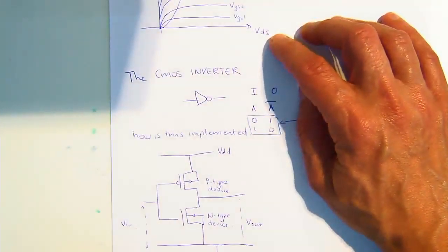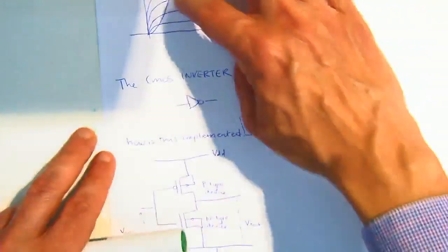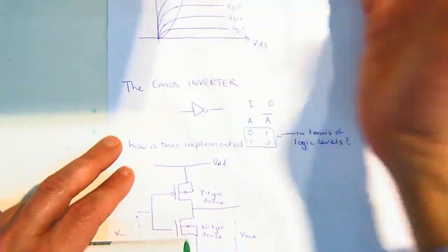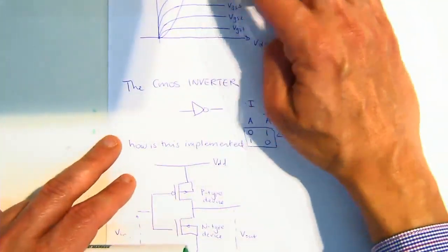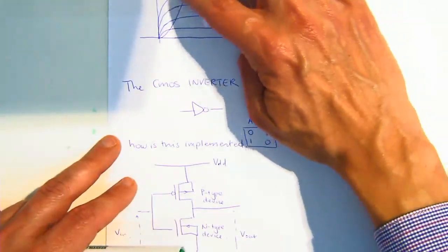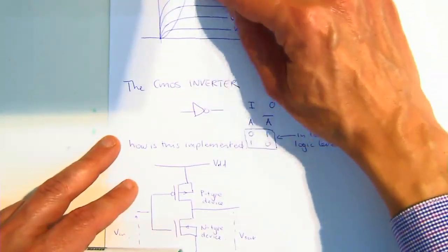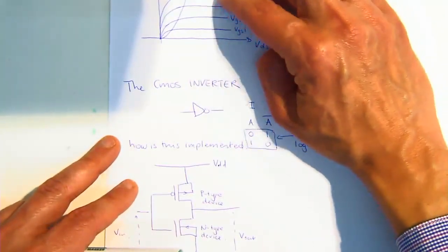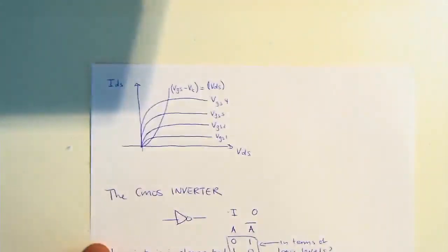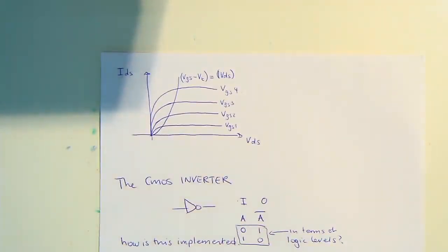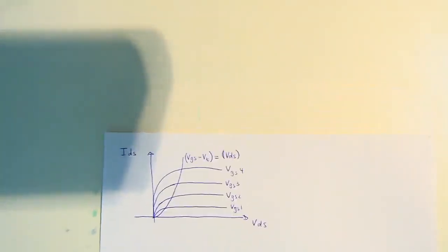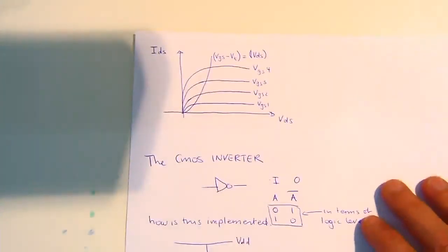Now, if you're designing this power amplifier, or any kind of amplifier, and you're in saturation, as you change VGS you're moving up or down these lines. Let me see if that helps a little bit. So essentially, you draw your load line, and then you're moving across those lines.